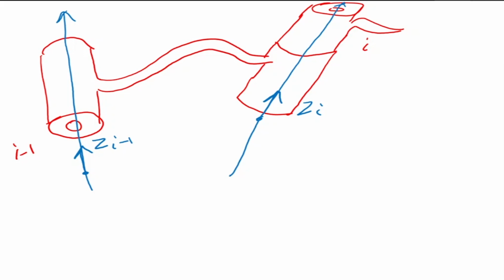We can notice that the z-axes have an angle between them, so I draw a parallel line like this, and I rotate z_i-1 by an angle alpha. So the first parameter is alpha. Now z_i-1 and z_i are parallel.